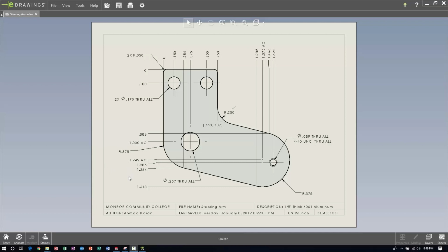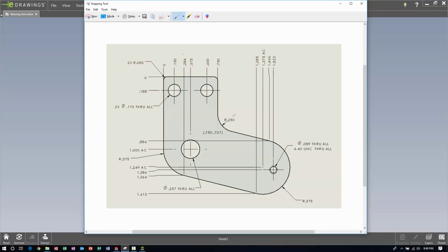Before I do that, the way I'm going to draw this in SolidWorks is I'm going to disregard the arcs at this point, just to keep my first sketch simple and straightforward. So I'm going to draw this line, a vertical line here, this line at an angle, and this line. Then I'll draw this line, add a parallel relation between these two lines, and probably add a tangent arc.